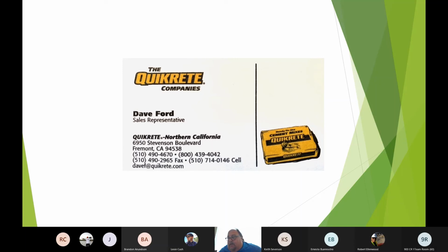There's a product called QMax Pro, and it's a concrete mix. It's got an hour's working time. You can walk on it in 3 hours, and it's 6,500 PSI, but it's not a fast setting concrete. You're talking about a high early strength walk on time of 3 hours, but you still have an hour of workability, and you reach 6,500 PSI. It's an air entrained cement along with fibers, and that high early strength is incredible considering that you're able to walk on it in 3 hours, and at 28 days you're at 6,500 PSI. It's called QMax Pro, 80-pound bags.